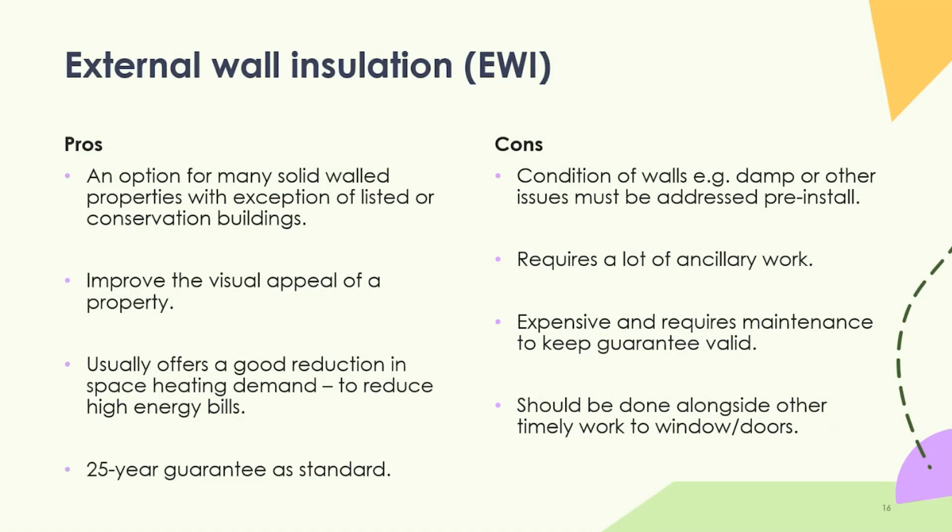presuming that those windows are double glazed, ideally treble glazed, but the windows should be moved out from being mounted in the brick and then be moved into the insulation layer, because that eliminates the cold bridge that you would get around the window, so where basically heat can still escape around the edge of the window frame if the window is still mounted in the brick.